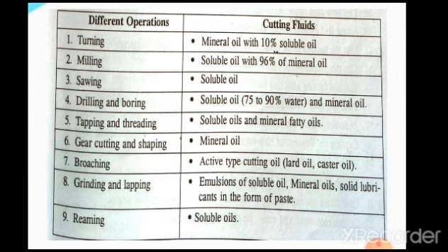And the last one, the reaming operation, which is known as fine finishing, internal. In that we can go for the usage of soluble oils. So you need to know what type of cutting fluids are used for what type of operation. That is very, very important.